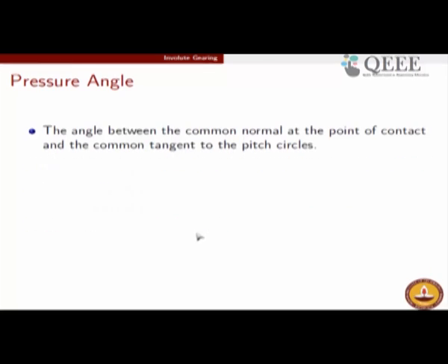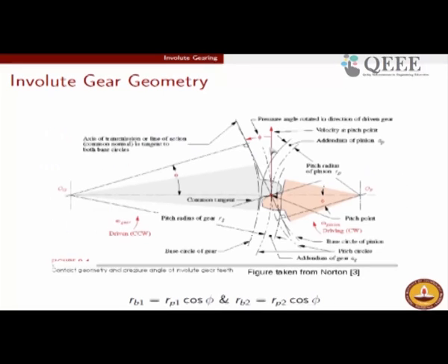So you lose a component of the force. The force that is being transmitted is in this direction; one component of it is towards the shaft direction, and the other component is perpendicular to the shaft. So this component, which is vertically aligned and pointing in the red direction, is responsible for the torque. So the F component acting here, you take cos phi of that, and this component will get multiplied with the radius and give you the torque transmission.